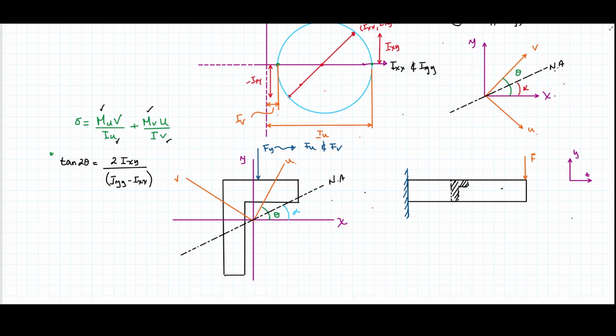So the deformation of it, if it's a cantilever beam, you can search in the tables. This is a typical case. We know the deformation of a cantilever beam is going to happen. I'm losing the pointer of the tablet here. Got it again. So the deformation of a cantilever beam is defined by the force times the length of the beam to the power of 3, divided by 3 times E times I. And this is a formula.